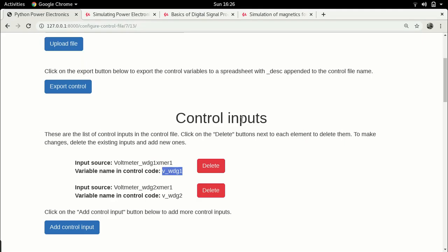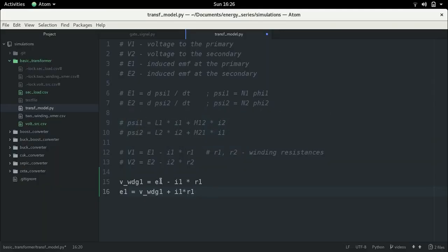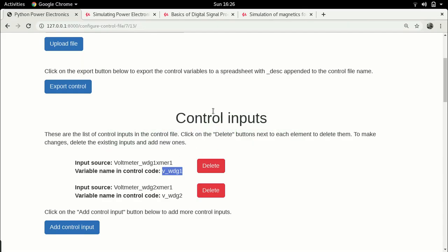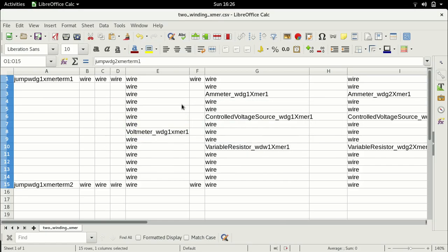That is very important. So really speaking, we got our equation wrong. Alright, so it is voltage, that is this one, the applied voltage minus this drop across this resistance is equal to induced EMF.